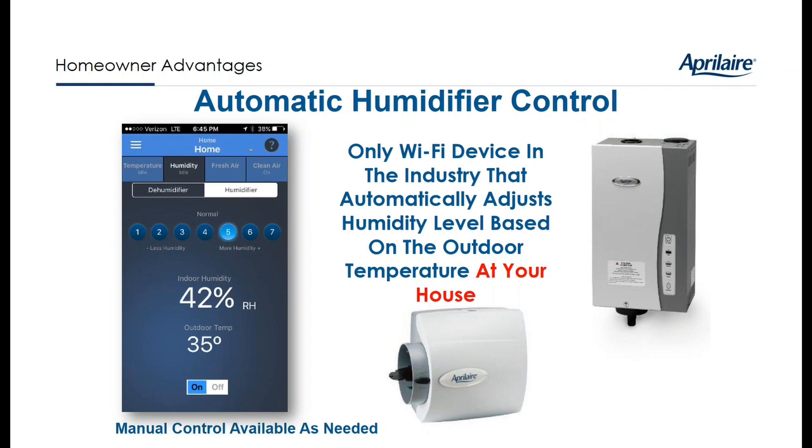The key here is it's going to automatically adjust the relative humidity set point without the homeowner doing anything based on changes to that outside temperature. If the contractor or the consumer prefers manual control, that's also available right through the app. So they could directly set the RH set point.